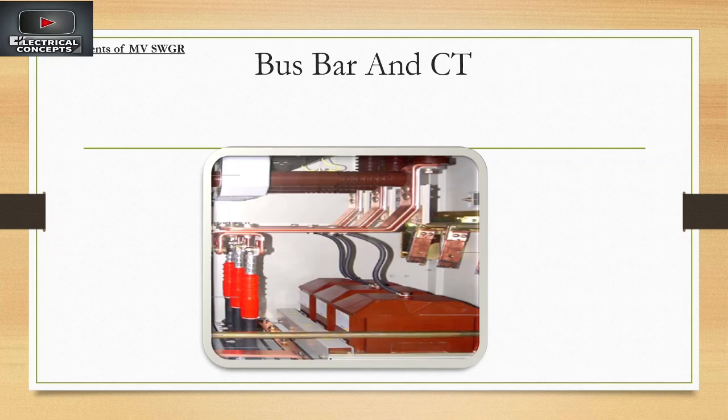bus bar. Bus risers. However, the bus is insulated here through the air, and these are just bare copper conductors which are bent according to the design. And the dimensions of these bus bars, these conductors, are designed in such a way to carry the maximum design load.